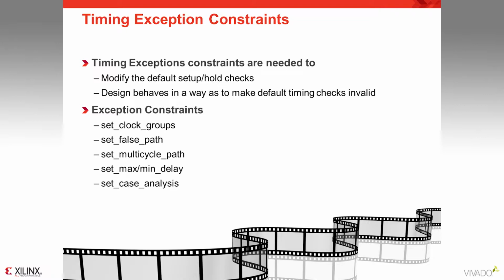The exception constraints are set clock groups, set false path, set multi-cycle path, set min-max delay, and set case analysis constraints. In this session, we will cover the set false path, the set min-max delay, and the set case analysis constraints in detail.